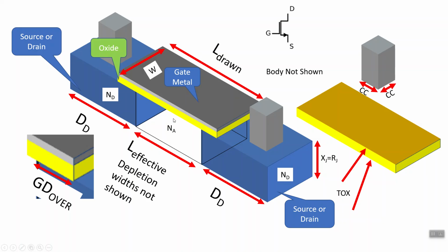That gives you the area times the capacitance due to the oxide. All right. So just in summary, the drain capacitance can really dominate everything. And we'll find that manipulating that, or avoiding charging and discharging it altogether, will save us some power later. But we don't normally think of things like this. It's a little too hard to draw.